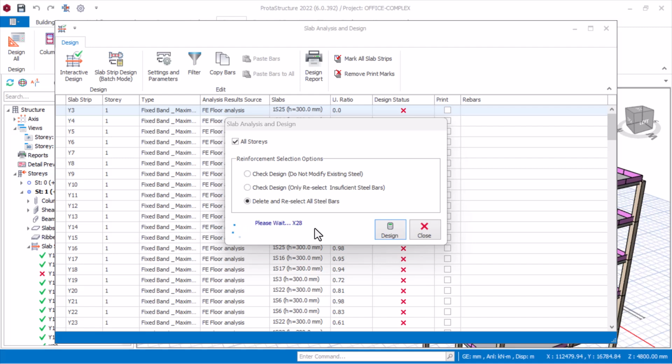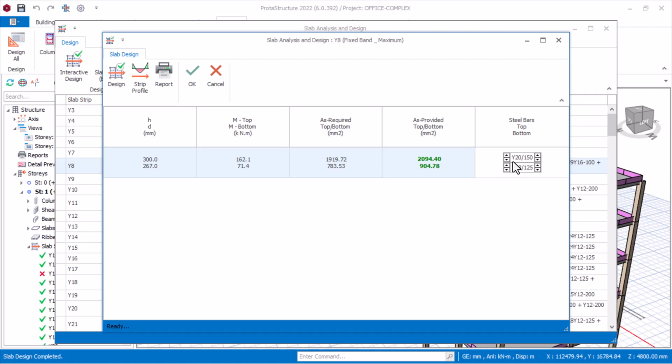So we are now trying to check if these structural members that we chose, the sizes, for example, the 400 by 400 millimeter column that we chose initially, the depth of slab of 300 millimeter, and the width of concrete wall, let me say 250 or 300 millimeter, are able to carry or withstand the effect of this load, and also withstand the structure and keep it in equilibrium. So we are going to check all this now.